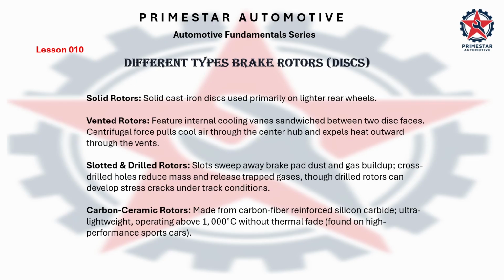Different types of brake disc or rotor disc. Solid rotors. Solid cast iron disc used primarily on lighter rear wheels. Vented rotors feature internal cooling vanes sandwiched between two disc faces. Centrifugal force pulls cool air through the center hub and expels heat outward through the vents.